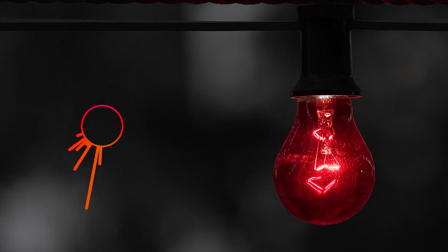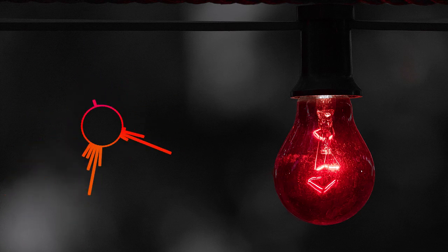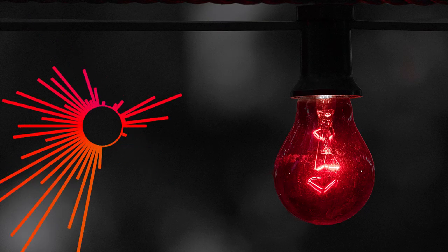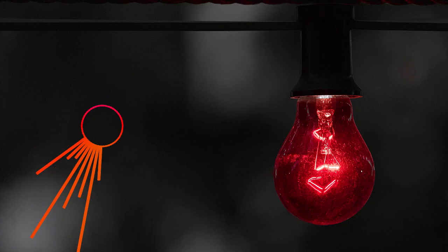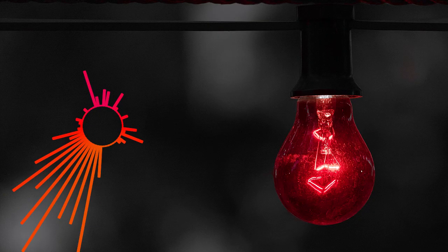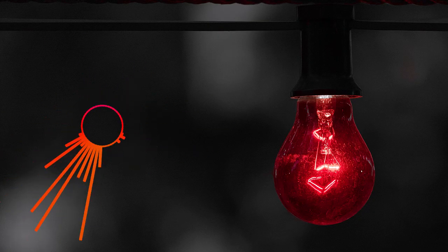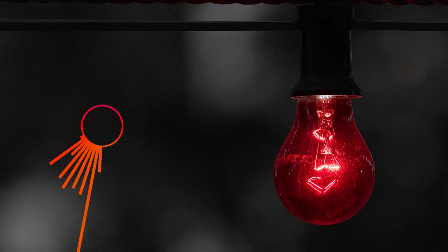They are powerful, bright, and very efficient, but they also create more heat than indicator LEDs. That's why they require proper thermal management, like heat sinks or specially designed housings that let heat escape safely. In short, these LEDs are designed for functional lighting, to light up a room, street, building, or workspace.